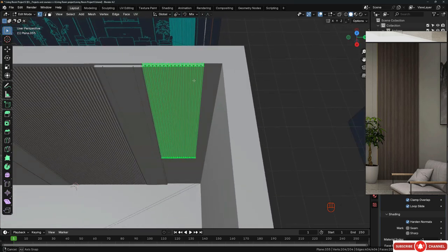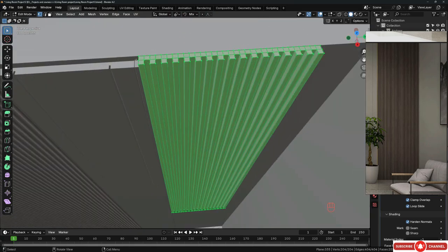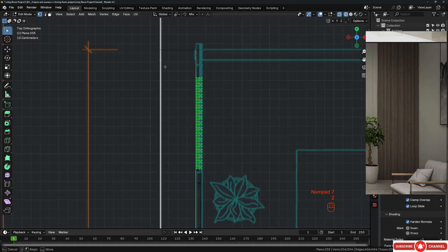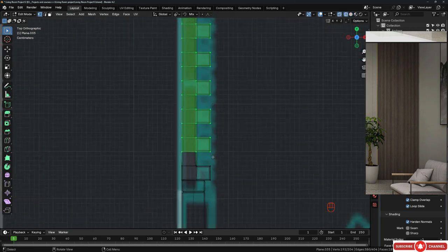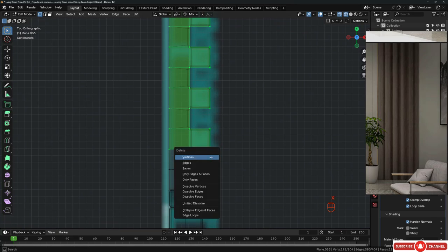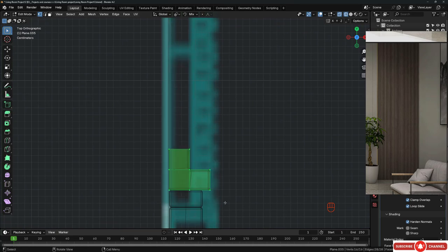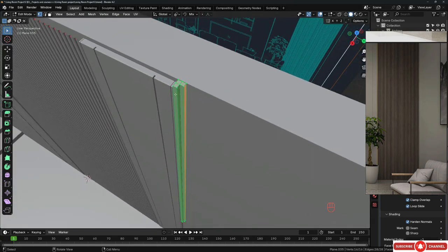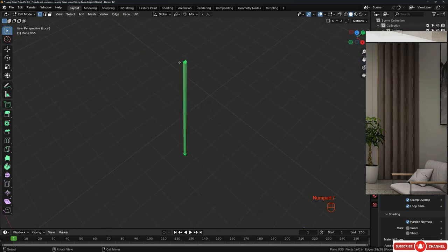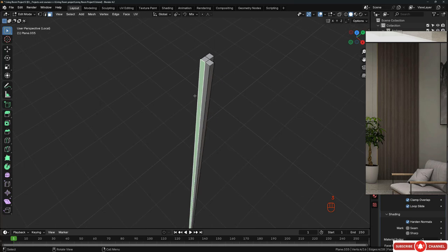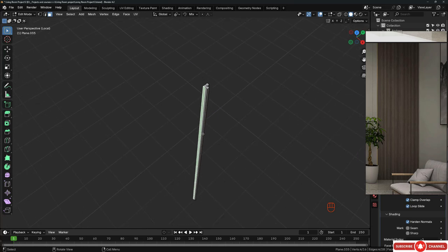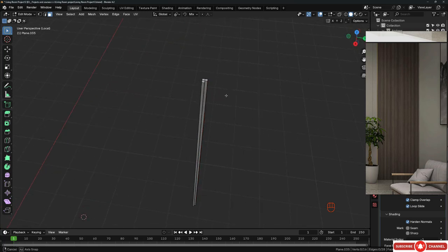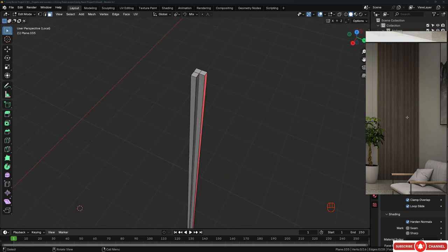All right, we just need to extend this a little bit. Actually, we can go to the wireframe and grab these vertices like that. Hit X and then F to delete all of these faces, and I just ended with this one, as you can see here. And I will hit select to go to the local mode because I want to delete this face as well. Hit X, F to get rid of it because I'm thinking of using array again here.